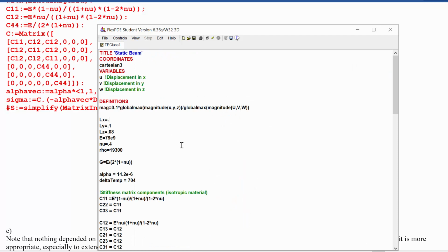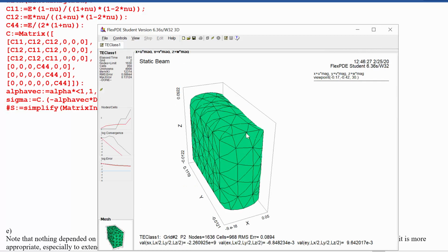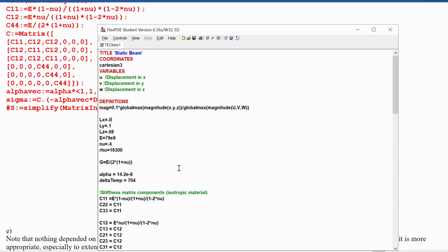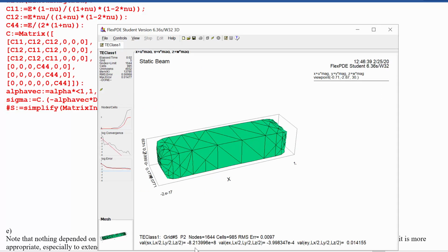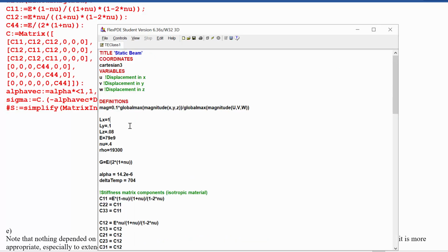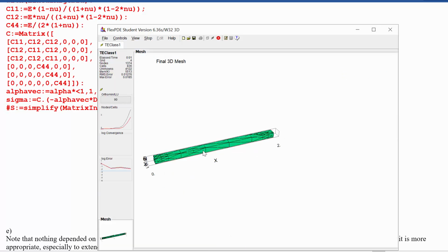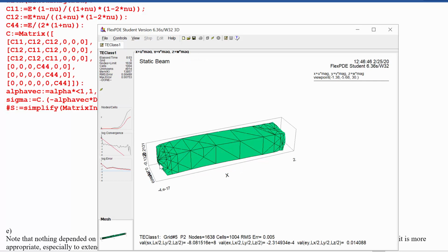If we were to take this low enough, then you'd expect that this is going to limit towards the 3.95 gigapascals that we had when we were not allowing it to move at all in Y and Z. On the other hand, if we take X longer, then it's going to limit in the other direction. It's going to limit towards the 790 megapascals as the anchors have less and less of a bearing on this thing.